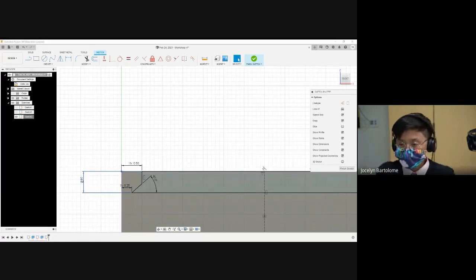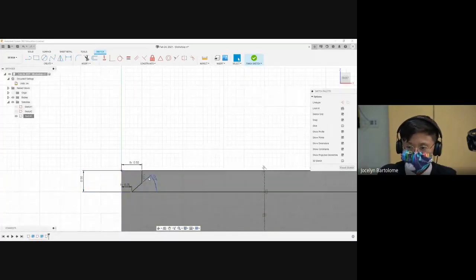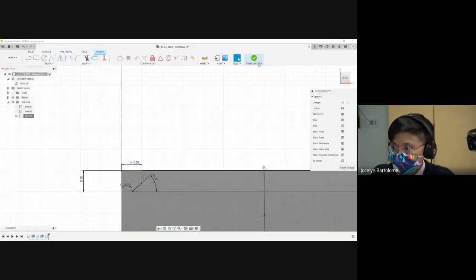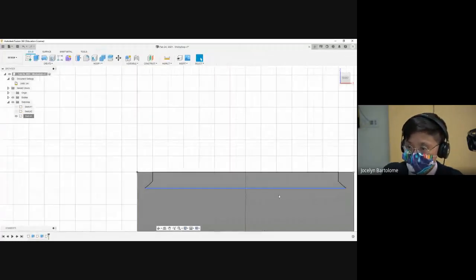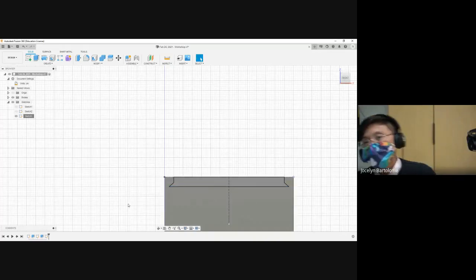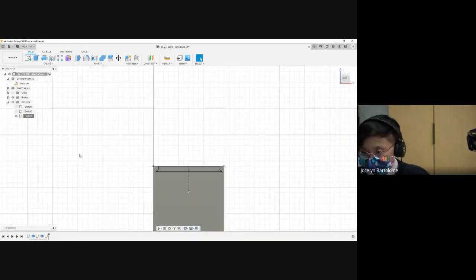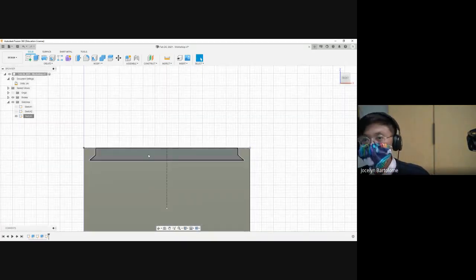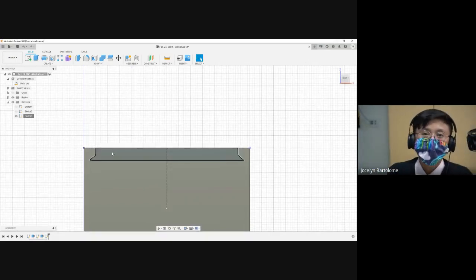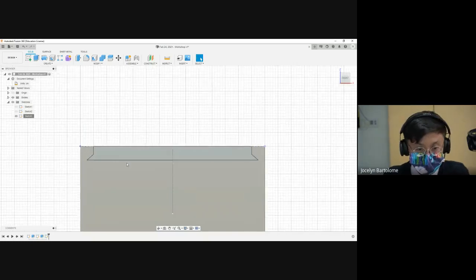Found it? Sweet. Did you want me to go over the function dimensions, like setting this fx to 0.5 and this fx to 0.25? No, it's all good? Perfect. So I'm just going to finish that sketch, and I'll tell you, in Fusion, black lines mean that your sketch is fully constrained, and blue lines mean that it's basically just missing information.